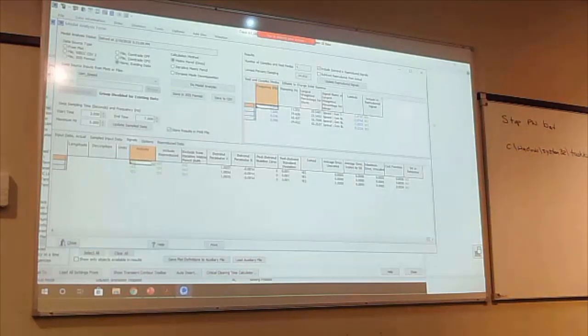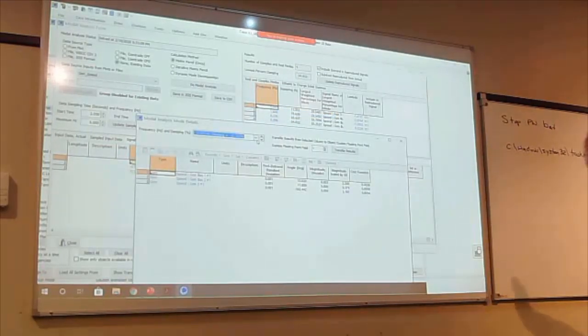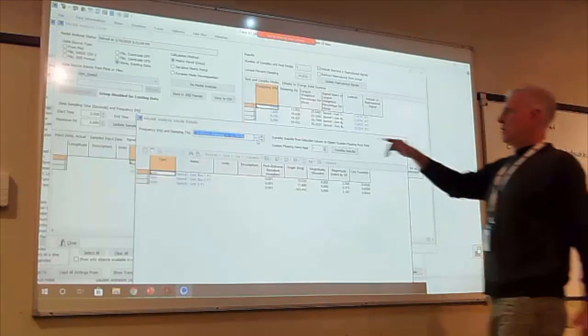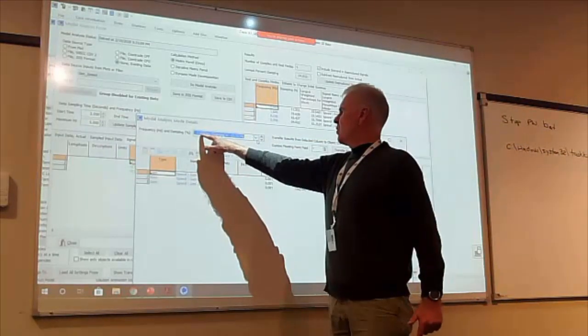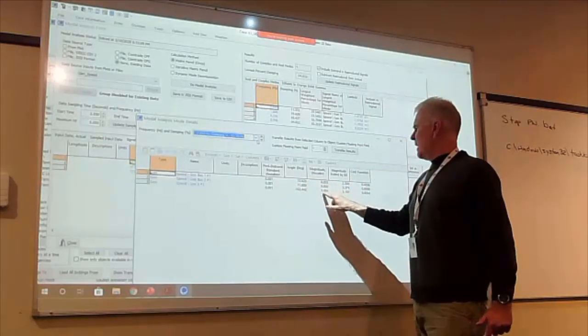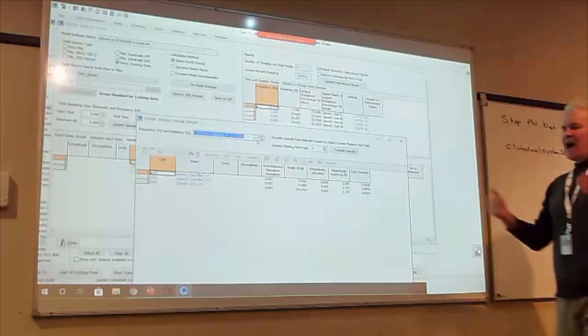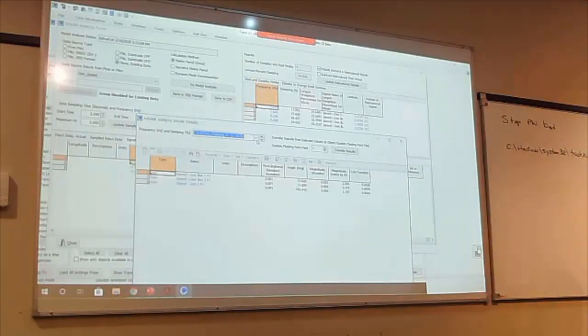If you want to know the details, you just right-click on that entry and do show dialog, and this says for each signal in this 2.05 Hertz mode, what was the unscaled magnitude and what was the angle of how that signal represented in that mode.